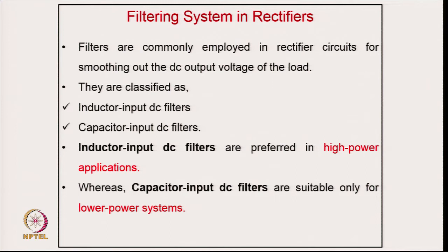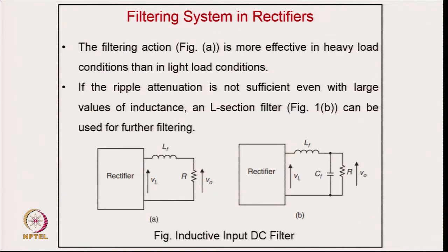So, you are using different kinds of filters, which we have shown in the circuit, and the performance changes with the filters. If you are using an inductive filter at the input supply, the current will be flat, and the crest factor will be less than for a sine wave. If you are using an LC filter, it is in between. But if you are using only a capacitive filter, the crest factor goes very high, and you draw a peaky current.